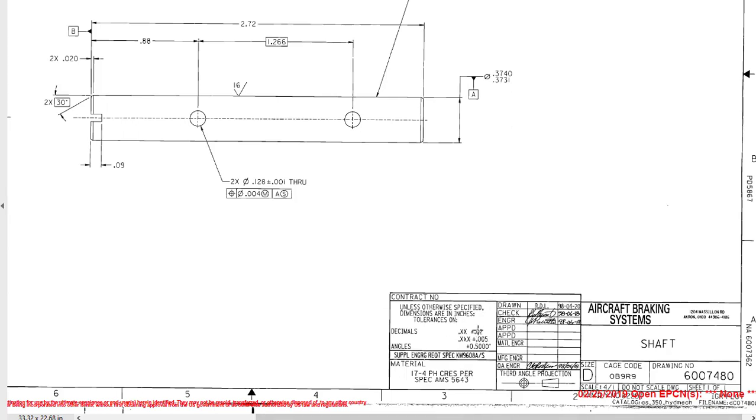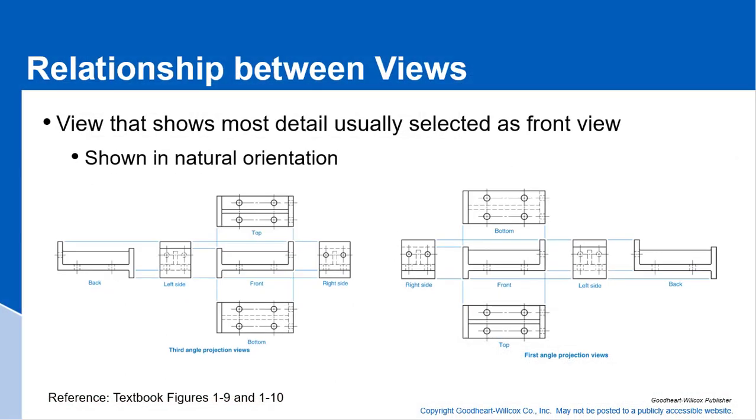Then we have a block tolerance designation here, the material, and then here is our third angle projection key. That says this view here and this view here are related to each other. In this view, I'm looking at this face of the part, and I see two concentric circles. So that's how we designate third angle projection.